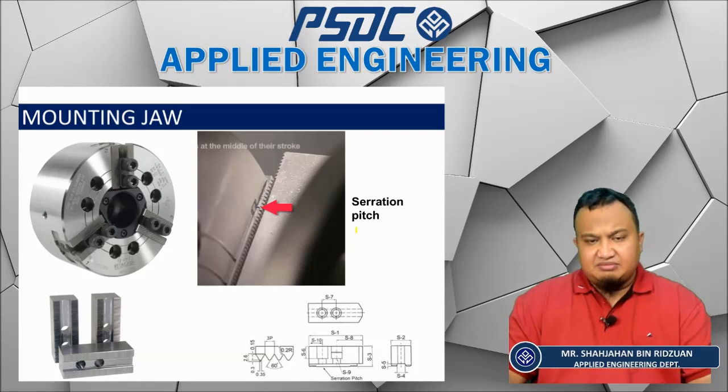If, let's say, you clamp the jaw unevenly, the rotation of the chuck is not even and causes vibrations to the machine.